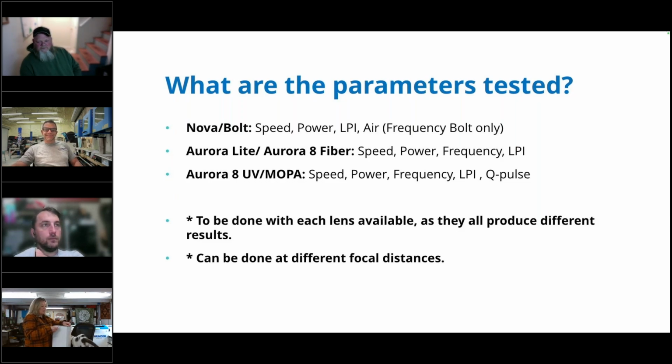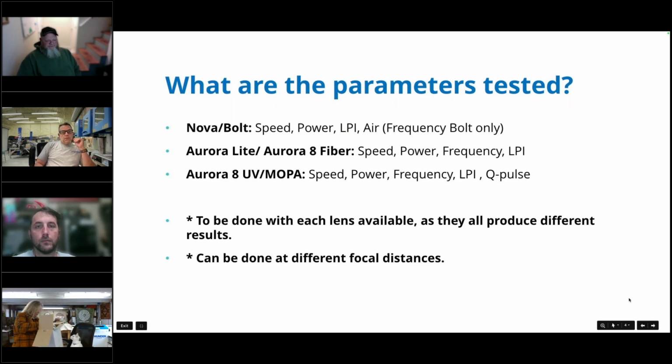But one other thing to consider, if you're cutting into or scoring, is min/max power, especially if you're going into sharp corners, to alleviate either burn through or bigger gaps. Correct. You want the min power to be a little bit less than the max, so that when the gantry or the laser changes directions, whether it's a curve or a 90-degree corner, you're not roasting those edges with too much power as the head slows down.